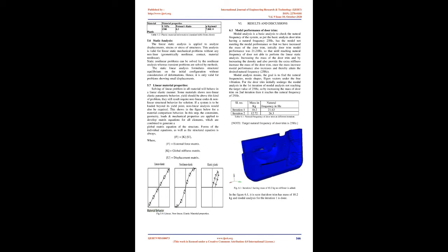3. This study helped in designing the plastic door module plate for car body application using 30% glass fiber PPLFT, Stamax registered trademark, material, and topology and shape optimization techniques. The final design of the plastic door module is 33% lighter with improved structural properties compared to the existing steel door module plate.